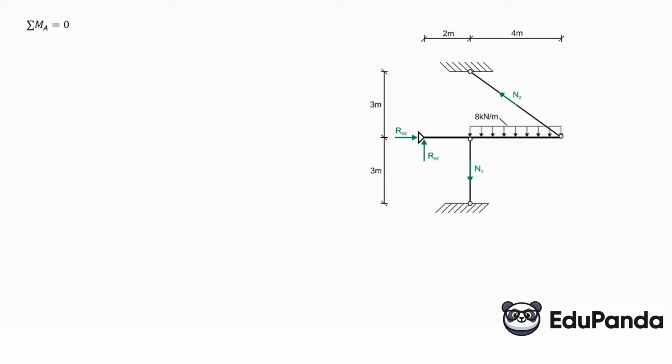Generally, I believe that it is worth decomposing forces that are at an angle into components. As I mentioned in previous examples or videos, if we denote angle alpha here, we have force N2, the reaction in rod N2. Here is some angle alpha. The component at which this angle is, the x component, is times cosine of this angle, and the other component is times sine of this angle.